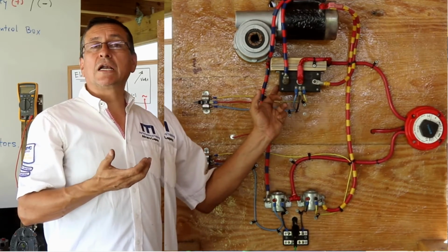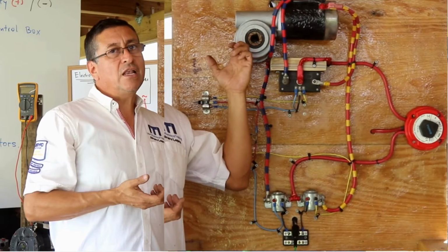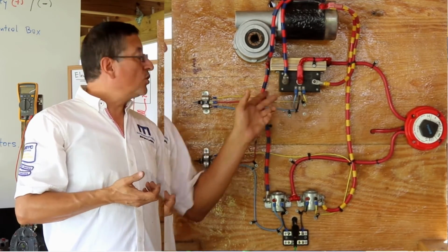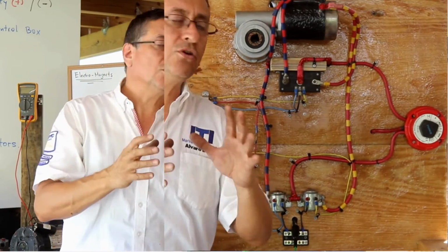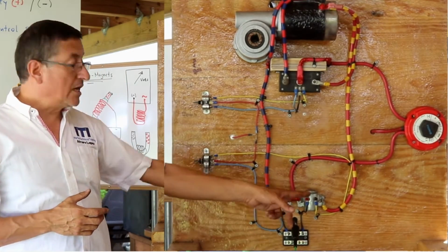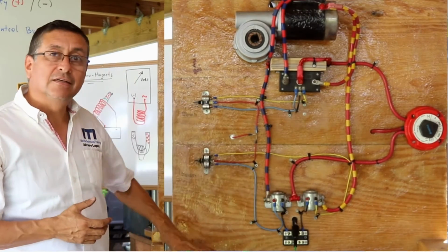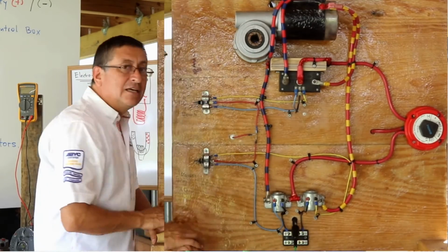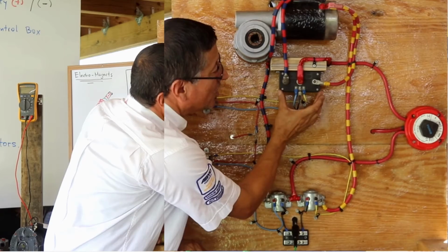In some cases you are in the middle of the ocean and you need to solve the problem for the windlass and you don't have an extra solenoid control box. You can replace the solenoid control box, for a simple situation, with a couple of relays. Those are automotive relays, $12 each one. You can replace this one with a couple of relays. Yes, you connect two relays in series parallel in order to do the same function as this.